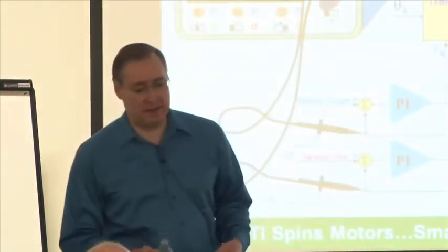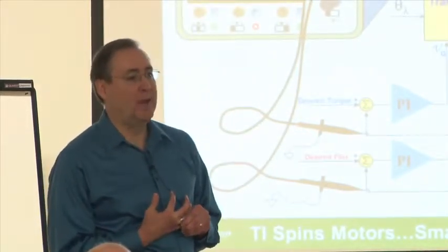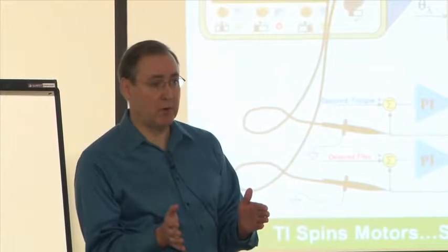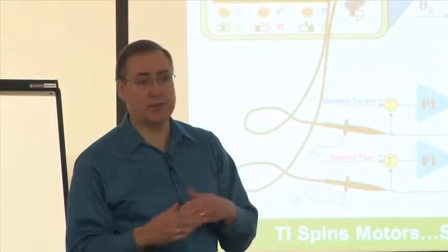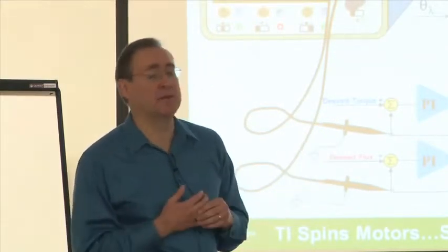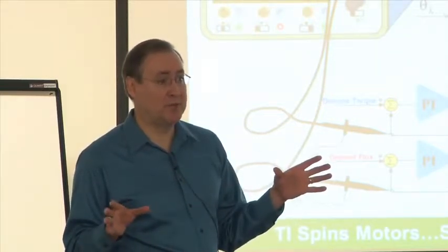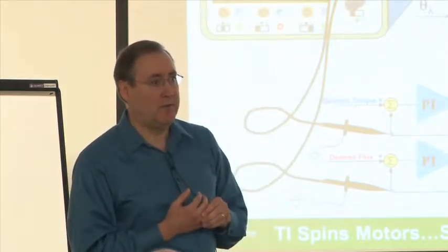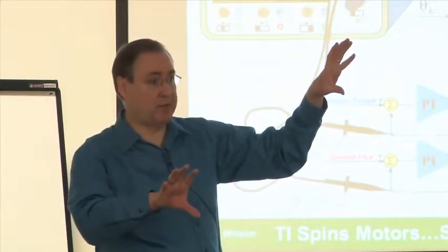Well, yeah. Obviously, when you get into multiple axis control, that does present a more taxing problem, because when you've done all the calculations for one motor, you've got to do them all over again for the other motor. You can't reuse part of the calculations from one to the other because the currents are different, the angles are different, everything else. The best you can do is, first of all, reuse the same routines, so you don't have different versions of the Clark-Park transforms. You just call them from one library. If you've got a coprocessor that can help, maybe the coprocessor does it for one motor and the main processor does it for another motor. That would be another way to do it.